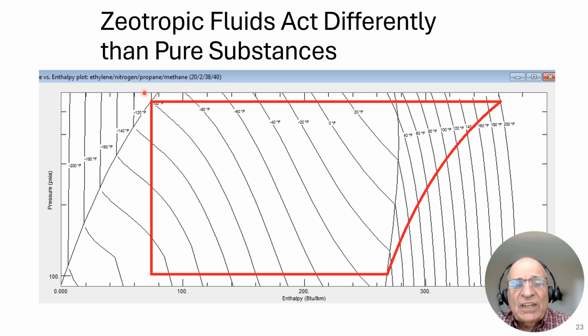Now let's go across a JT valve. What's going to flash off preferentially? Your nitrogen and your methane are going to flash off preferentially. So you go across this JT valve and you get them down to this much lower temperature. Up here we were minus 100 degrees Fahrenheit, and here we are minus 170 degrees Fahrenheit. What I did was I just looked halfway between here and here. This was minus 160. This is minus 180. So I'm down at minus 170 degrees Fahrenheit.